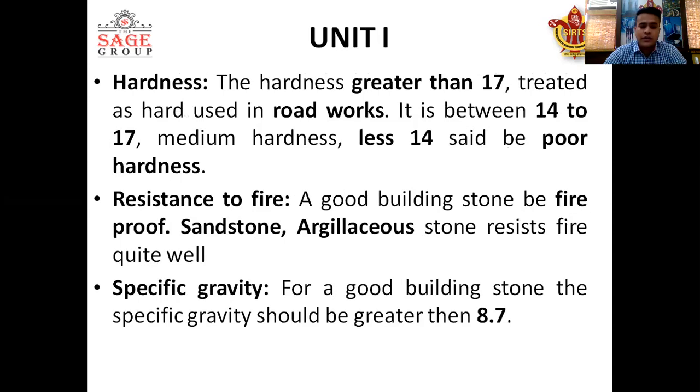Now the hardness. As we know, stones are very hard and have a greater value of hardness, so they can resist any kind of force acting on them. Let me tell you about the hardness index, so that we can decide whether the stone is suitable for our construction work or not. First, if the hardness of the stone is greater than 17, it is used for road work.